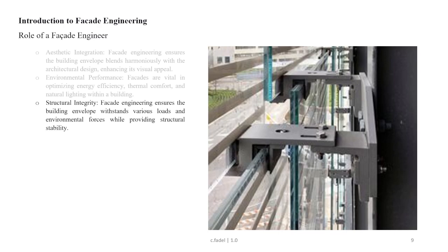stable and safe. Another thing that needs to be considered in the structural design is the impact resistance of the facade. There would be some potential impact loads from sources like debris, accidents, birds or migratory birds, or extreme weather events like a storm or typhoon. And so therefore the engineer assesses the facade's ability to resist these impact forces and incorporates protective measures such as impact resistant glazing, for example, or reinforced cladding system to mitigate damages and maintain the envelope's structural stability.